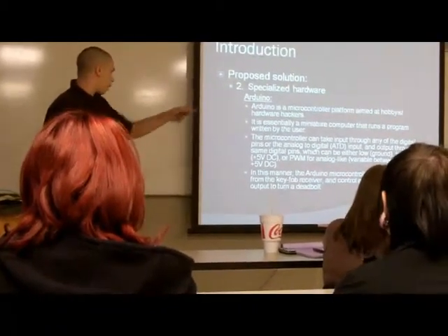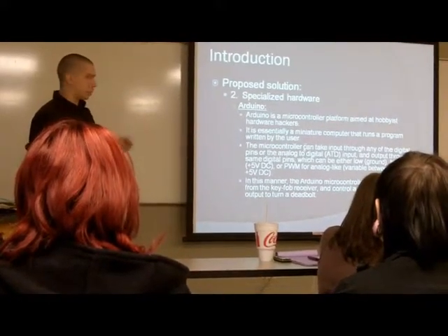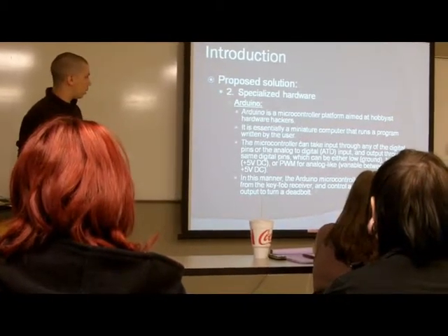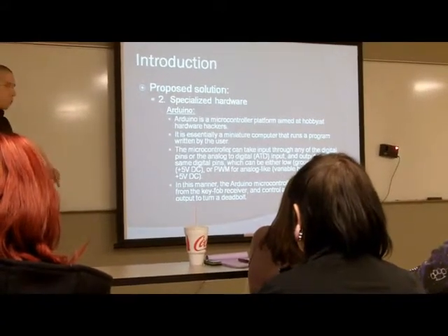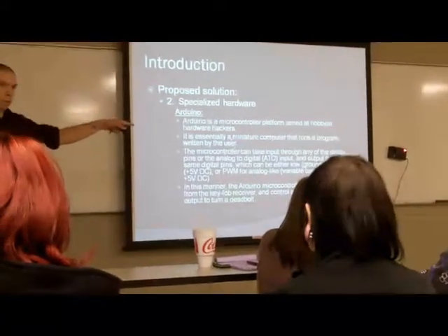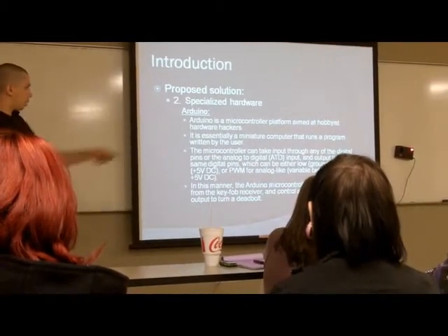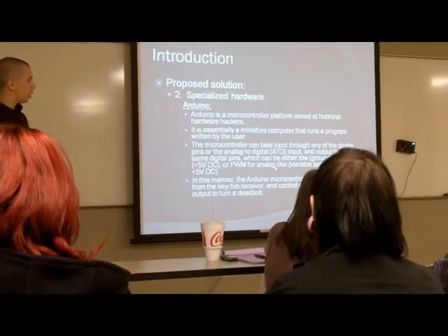So what I've got here is the controller actually takes input from the receiver that this is synced to, and it sends that to the Arduino. It says, okay, that was the lock button, so I need to run the lock function, which controls the servo using a PWM output, a pulse width modulation, and does a little speaker tone, a different tone for lock and unlock.